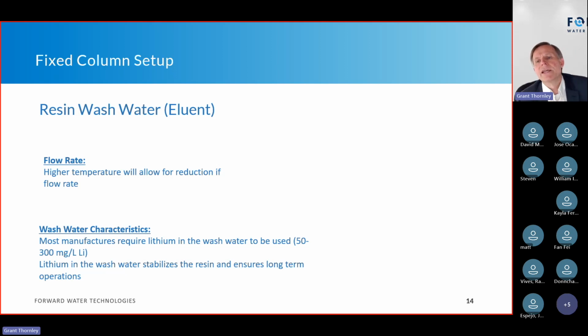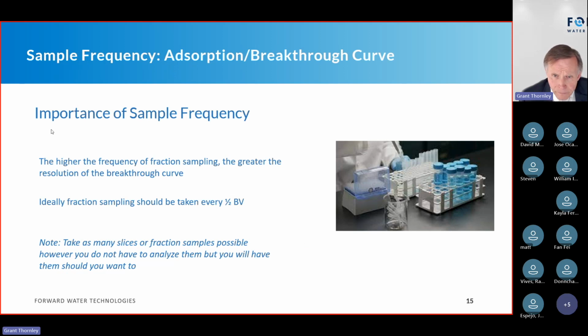And one other key thing is that if you're putting lithium into the wash water, make sure that the lithium is accounted for in the mass balance when they're calculating the recovery rate. I've seen a couple of times that they don't do that. The lithium looks great because they're not accounting for the lithium that they're putting into the eluate. It's a quick little thing for you.